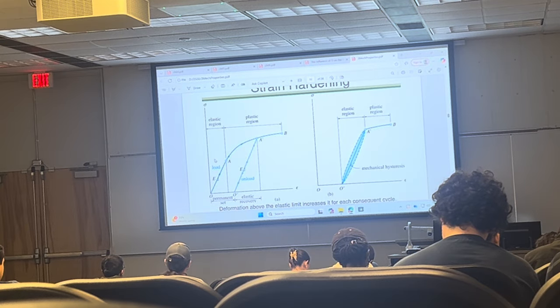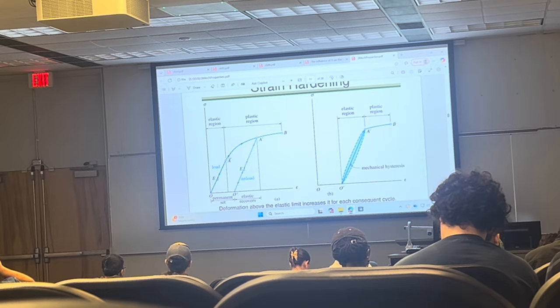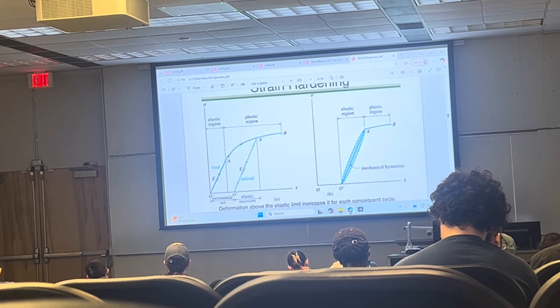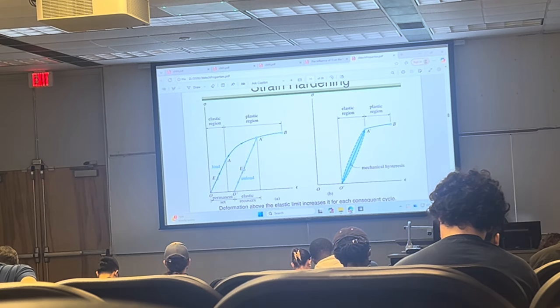Because the stress is measured in pascals. Pascal. And what about the proportionality constant between the stress and the strain, where strain has no units? What would be the units of that? Also pascals, because on the y we have pascals, on the x we have no dimensions. So each data point on this curve has the units of pascals, and the slope, this slope. And when I meant unloading is always elastic, you see this? This is the unloading.